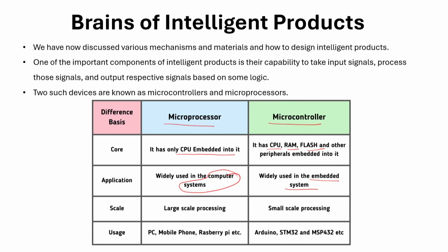Why do we do it? Because microprocessors are required for large scale processing, but an intelligent system on its own does not typically need large scale processing, unless you network it, and then of course you can use cloud computation in order to network the system. So, microcontrollers can be used for small scale processing. You have a few sensors, one or two or few actuators, and then you want to have a closed loop system with them.